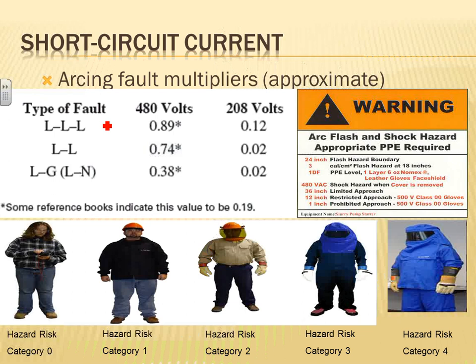That's the unlucky one. If you have a high impedance short or ground fault, it's going to sit there instead of tripping, because there's an impedance in it high enough to prevent the circuit breaker from tripping fast and low enough to create arc and spark inside your equipment and burn it. That's where you get yourself into arcing faults.